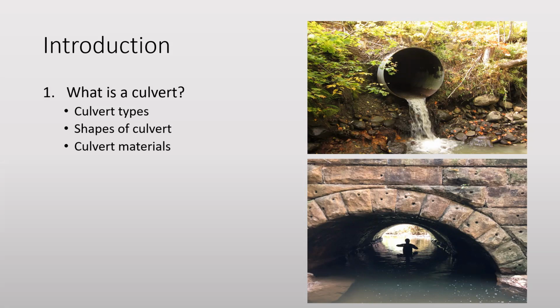When we hear the word infrastructure, most of us think of roads and bridges or railroads. However, supporting these roads, bridges, and rail lines are countless drainage structures that are classified as culverts. They are buried pipe, box, or arch structures that are open at both ends to convey water under the traveling surface. They can be structurally similar to bridges, but are defined as having unsupported spans of less than 20 feet.